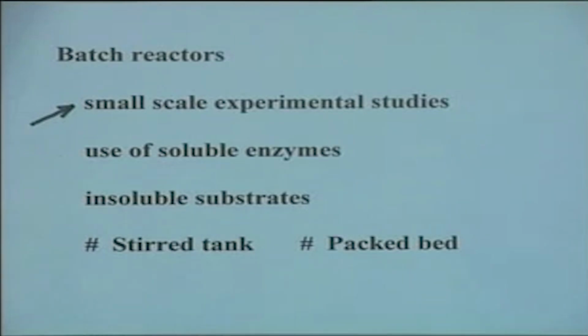Now in the case of a soluble enzyme, the enzyme cannot be separated. So most of the enzyme reactions that require crude enzyme preparations, where no degree of purification is needed, particularly for food or beverage productions, the soluble enzymes are added, and they carry out the reaction and go along with the product stream, and the enzyme is not required to be separated. However, if we use an immobilized enzyme preparation, the separation of the enzyme is feasible by filtration or centrifugation, and you can reuse it.